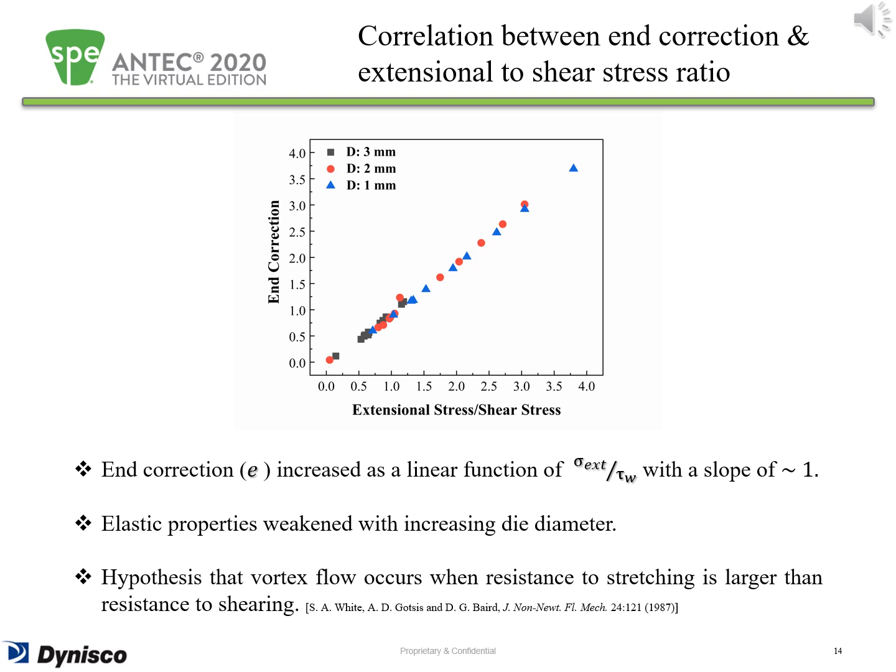Moreover, the elastic characteristics of LDPE melt were reduced with increasing the die diameter. The reason is that the contraction ratio, which is barrel diameter to die diameter ratio, is smaller for bigger diameter dies, leading to the reduction of entrance pressure drop and these elastic properties. The results from this figure confirm further that extruding through a bigger diameter die favors extensional flow deformation of polymer melts due to the existence of high resistance to the shear flow deformation by using bigger diameter dies.